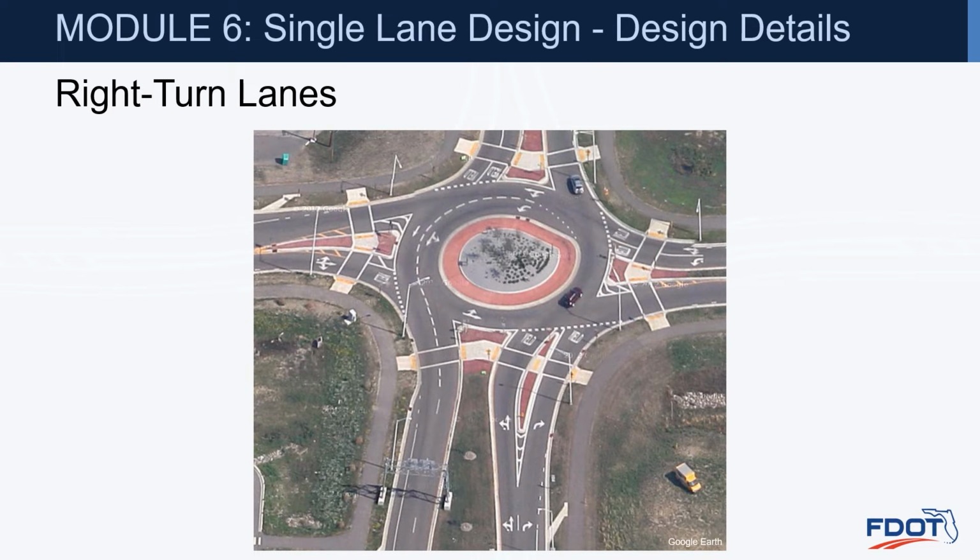Here is another graphic of, in this case, a partial right turn bypass lane. And actually there are two lanes approaching this roundabout, and the rightmost lane is becoming a right only, so really kind of dropping a lane. But I'll just ask, is this right turn well designed, or is it snagged, or is it actually easier to get into the circle in that lane as opposed to the one that they're supposed to be in, which is the left, the through. So this one you'd want to look to put a little more curvature potentially on that right turn and try and snag it a little bit better and get it directed at that splitter island.